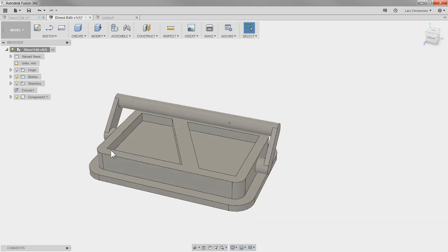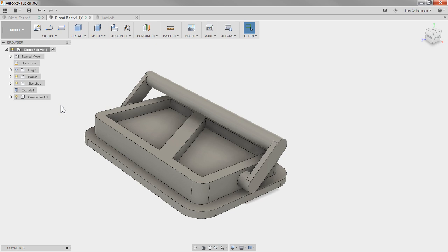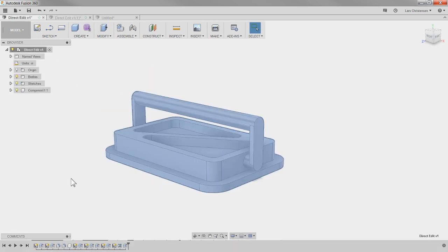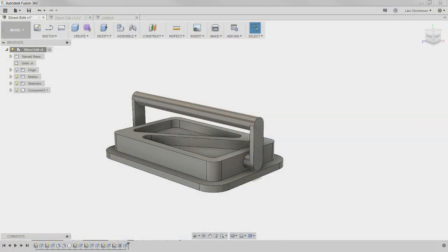So that's direct editing inside of this. Well, this is direct mode. This was the imported part, but it actually also works with direct editing on the parametric parts right in here too. There was nothing I just did that was magic just for direct editing. But that's where I would say you normally would use direct editing: inside imported parts. But you could do many of these things right inside of a parametric part too. It will just be recorded, right?